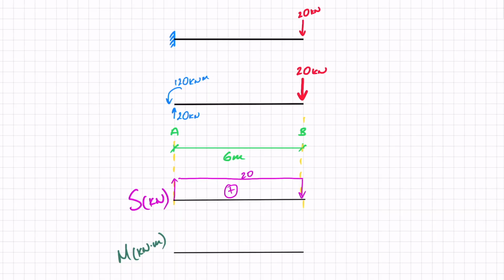So example number 2 is this cantilever beam with just a point load at the very end. We've solved the reactions, so there is a moment and a shear reaction at A. We've already found the shear force, and just like before, because there were only point loads, this is just a constant, which once again means that my bending moment has to be linear, right? It's one rank above. If I was integrating a constant, I would get a function of x. Now, this one is pretty simple, because I know that at the very end I have to end with 0, and I know that at this point here, point A, I need to start with that moment.